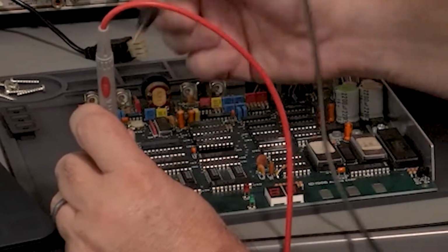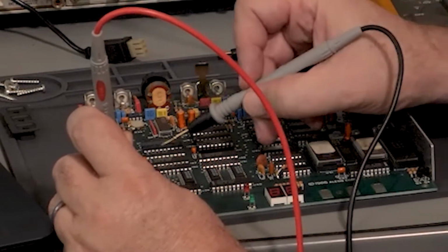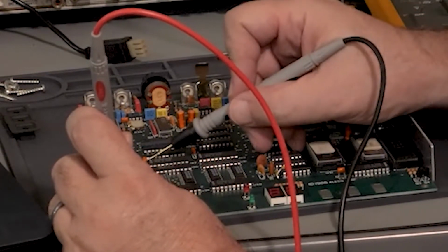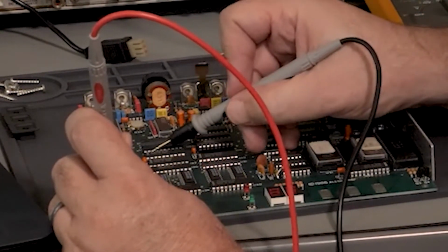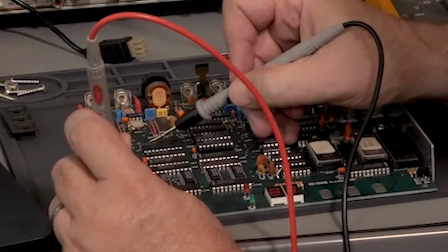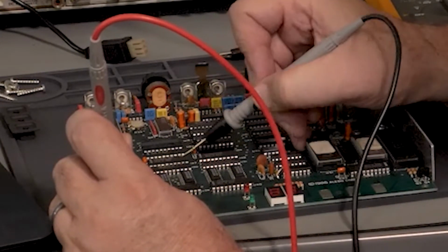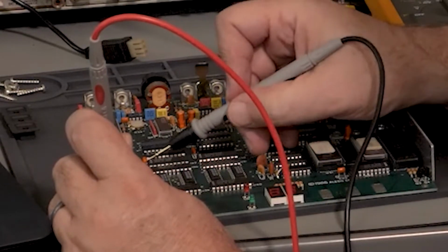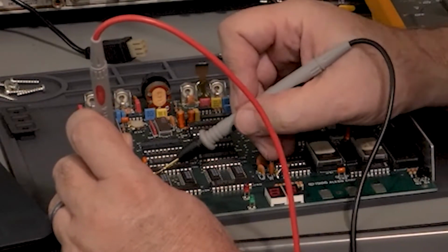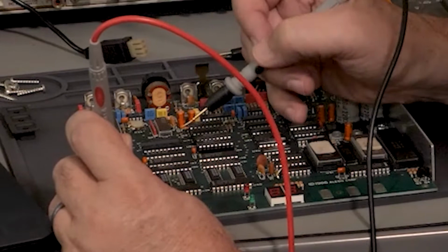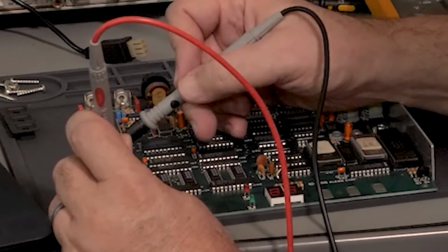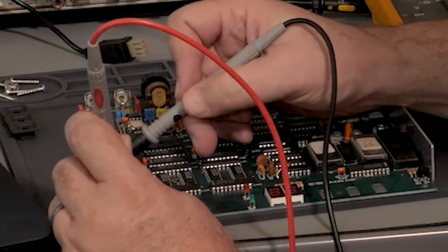So that's pin 2. So we're going to call a sweep, and a sweep, if you can see, is I'm just going to take this probe and rake it, not real hard, I'm going to scratch the board. I'm going to rake it across these chips. Not too fast, but enough where if it's connected, I'll hear a little blip. All right? So it's not connected anywhere up here. All right? It's not connected.